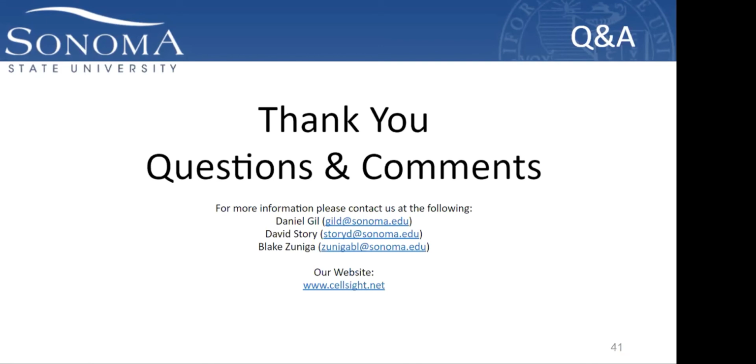Okay, I'm unmuted now. Great work, guys. Really interesting. I'm particularly interested in the SDR, not surprisingly. You mentioned that you had a noise floor of minus 130 dBm. I'm sort of surprised at that. I'm not quite sure what you mean. Is this the displayed average noise level, if you were to use spectrum analyzer parlance? Because the HackRF is only an 8-bit SDR, and so theoretically it's only got 50 dB of dynamic range. Did you look at other SDRs, and would extra dynamic range by using a 12 or 14-bit SDR have improved your performance, do you think?